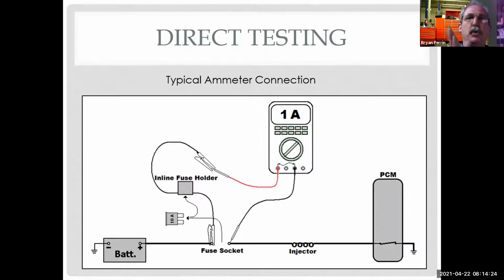So we test for voltage in parallel, right? I'm measuring two parts of a complete circuit and measuring the voltage difference. So I'm measuring in parallel. Here, I've put the meter in as part of the circuit, so I'm measuring in series.